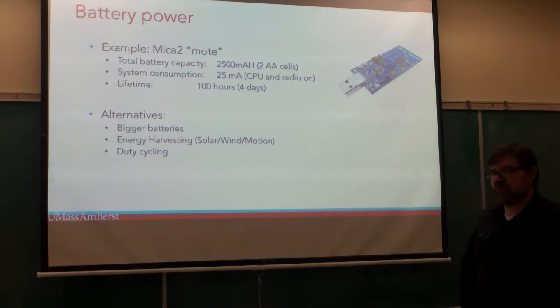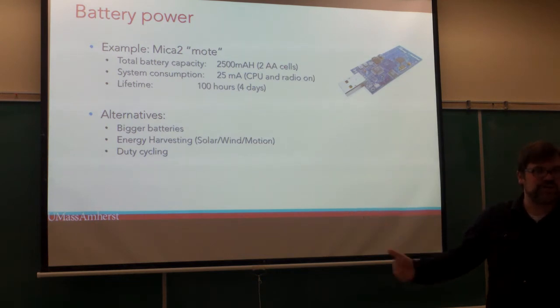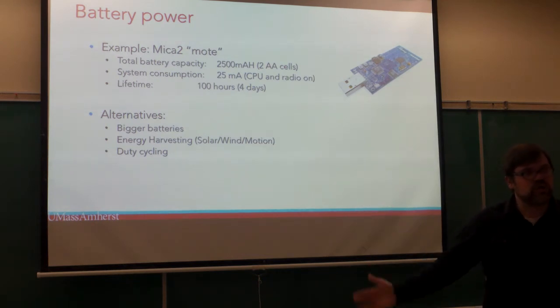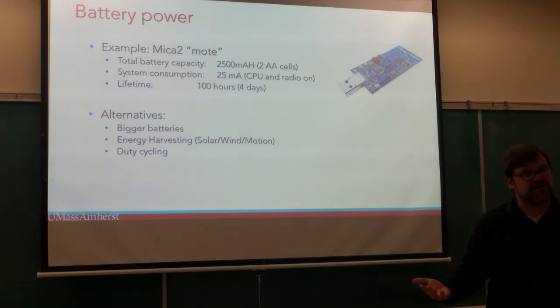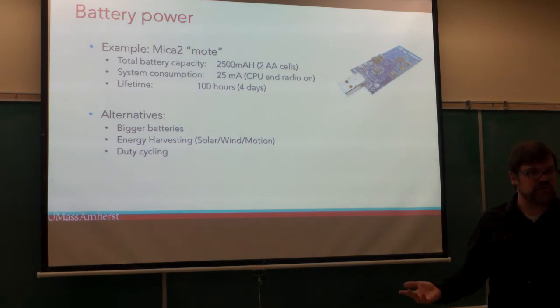And then duty cycling. Say I mentioned the radio receive circuit earlier. The thing that you wouldn't want to do is, if no one has any data to transmit, continuously have your receiver active, because you would be drawing something like 25 milliamps of current and getting no benefit from it.